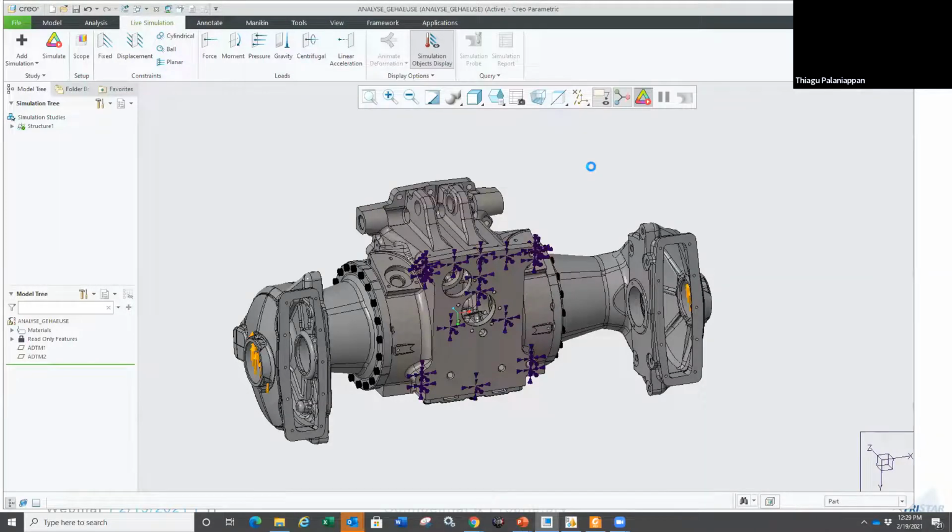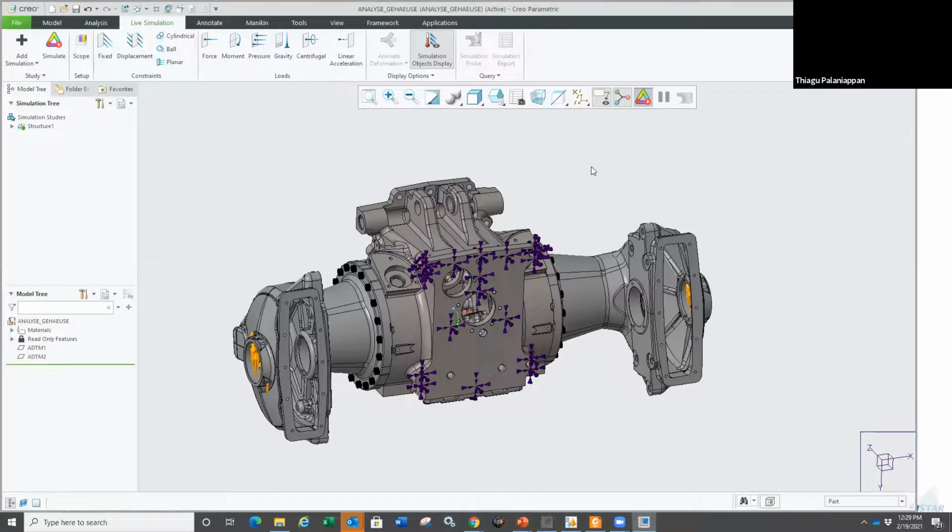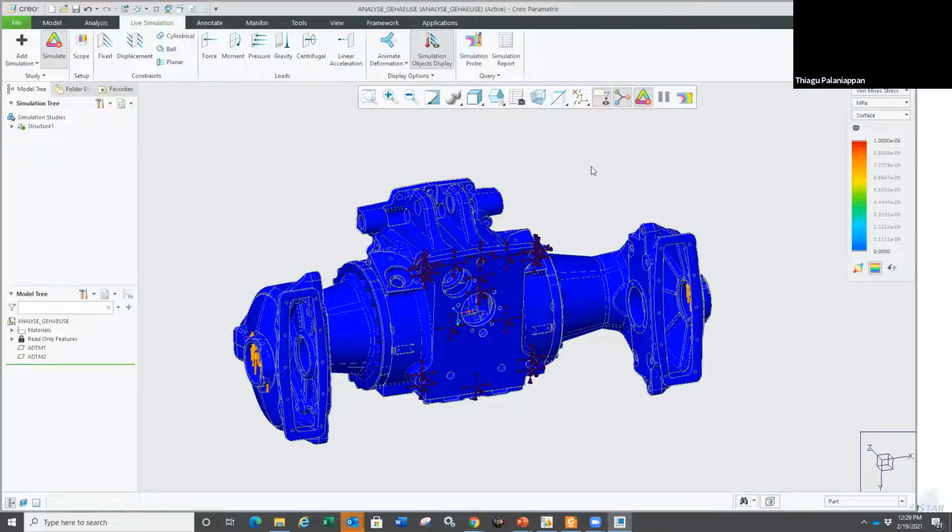It is running. It's leveraging ANSYS's proprietary Discovery engine working behind the scenes in here. It's leveraging your GPU, so you will need an NVIDIA CUDA-based graphics card, because that's very important. It's a prerequisite to use Creo Live Simulation, since it's not using the CPU, it's using the GPU.